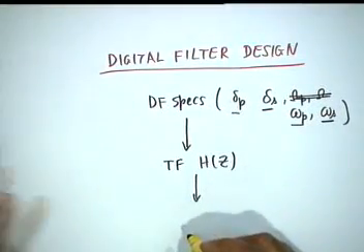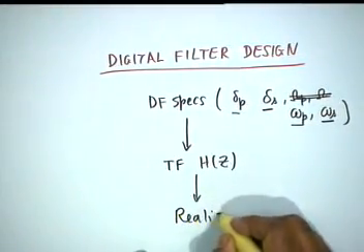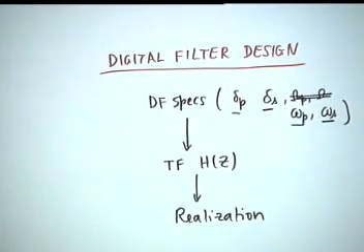Okay? So, the transfer function has to be found, and then once you obtain an h of z, then with the knowledge that you have already acquired, you realize it: you go either to software, write a program with a dedicated PC, or use a programmable chip and program it, or make ab initio hardware realization. If it is very simple or very complicated, it is either extreme, then you design your own chip and fabricate. If it is in between, then you try to use one of the TI or AD or some other chip, AT&T.